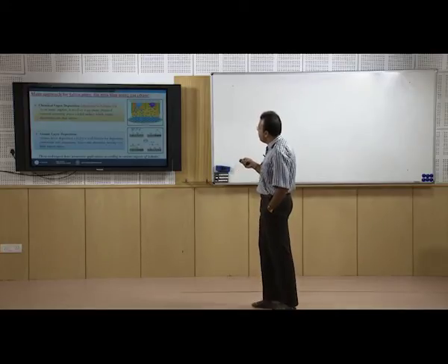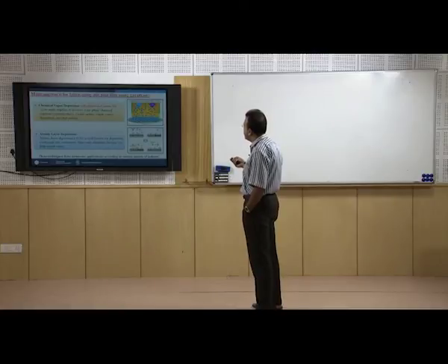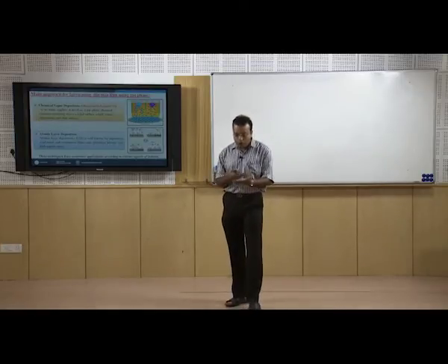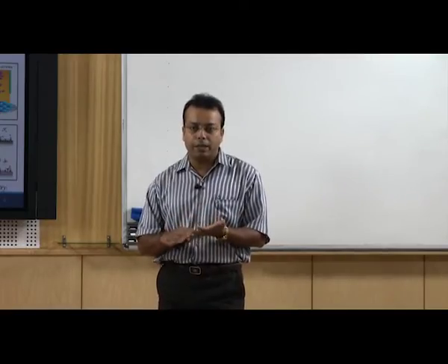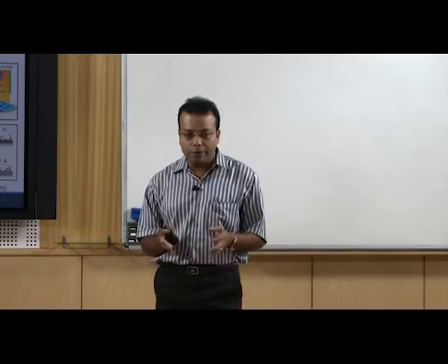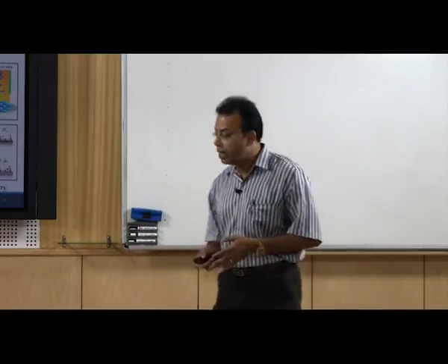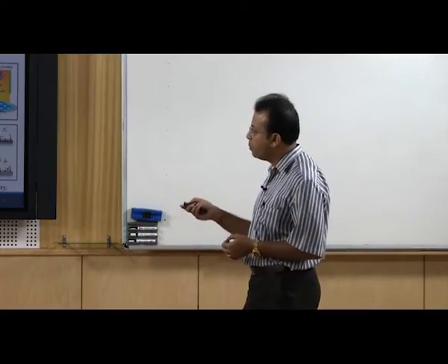If you remember, here we use different kinds of vapors, for example vapor of methane and vapor of hydrogen. They go and react on the substrate and form a new material on top of it. Since we follow chemical reactions here, it is known as the chemical vapor deposition process.